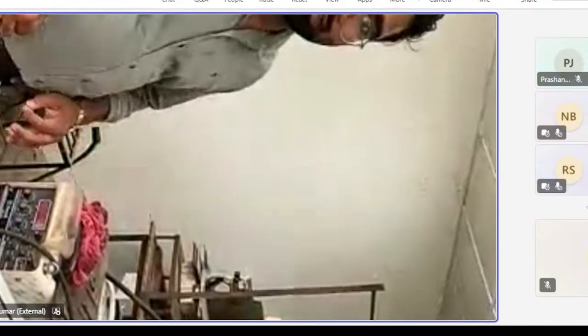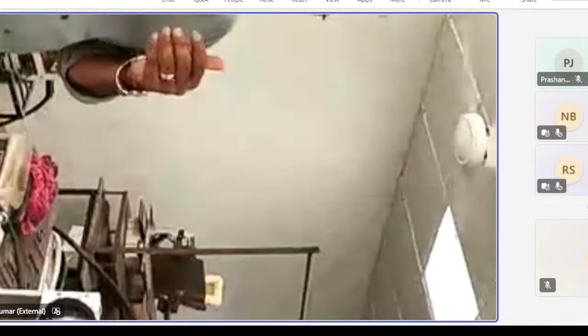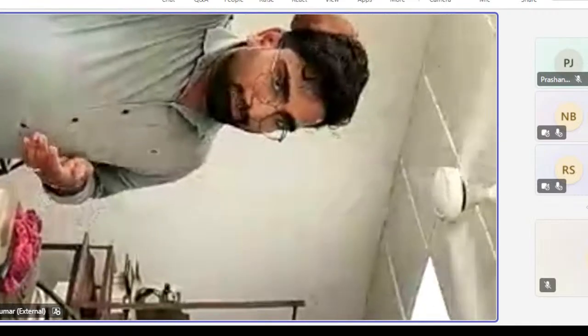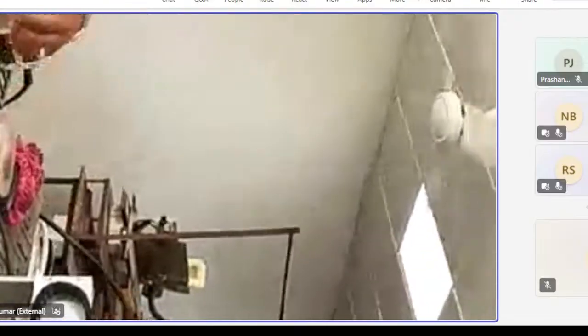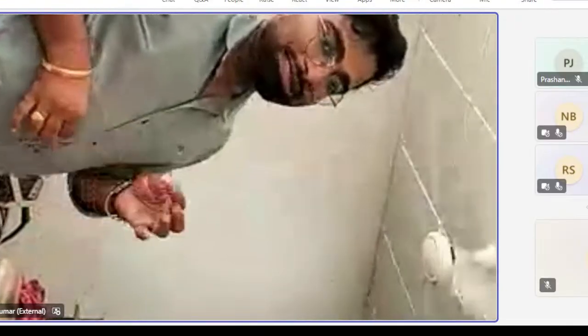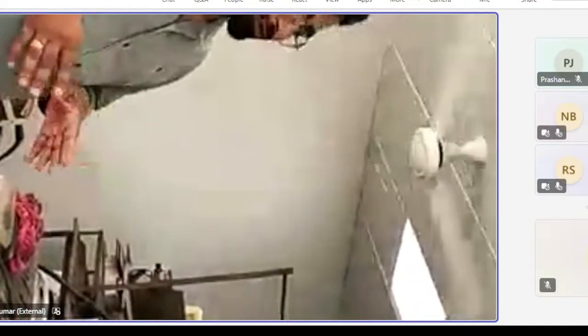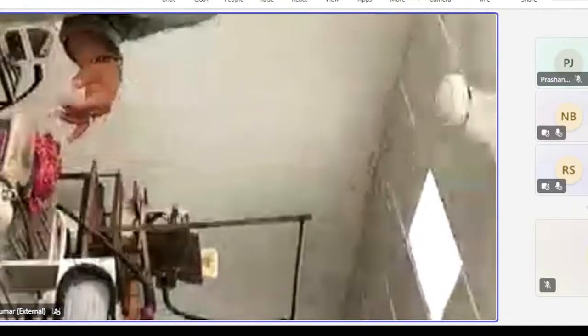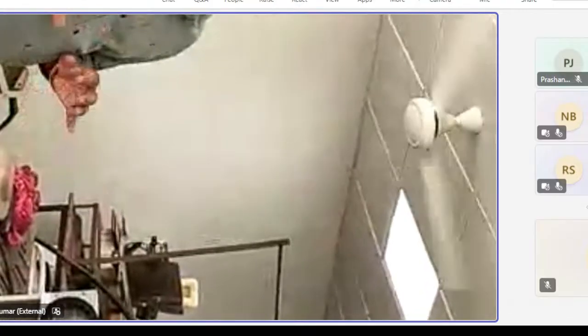This basically shows the typical diameter of the wire that you are using before the deposition. If your wire diameter is 0.8, then you have to fix it at 0.8. If it is 1.2 or 1.6, then you have to change accordingly. So these are some basic considerations that have to be kept in mind. Otherwise, during the operation, even a single mistake will lead to complete experimental failure.